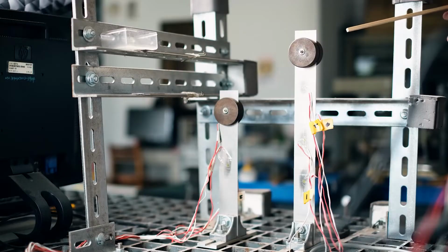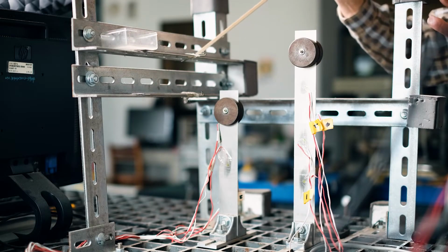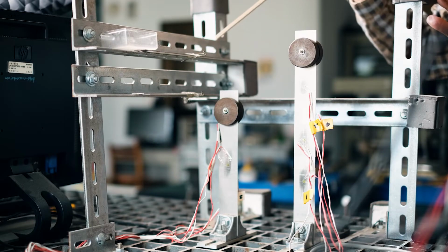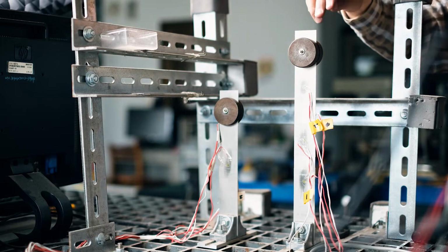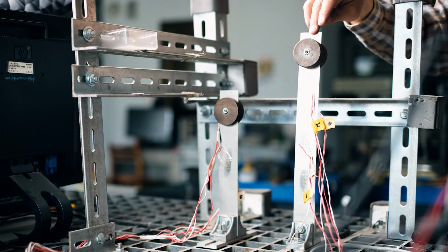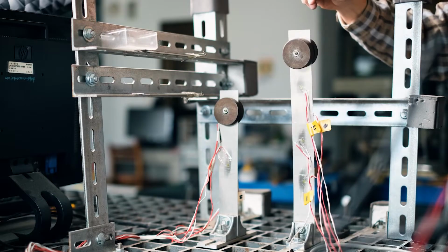Before starting the experiment, make sure the steel plates are completely still. After your partner is ready, laterally push the 30 centimeter steel plate back 2 centimeters. Use the steel ruler on the side to measure the distance. Let go of the steel plate when your partner signals.